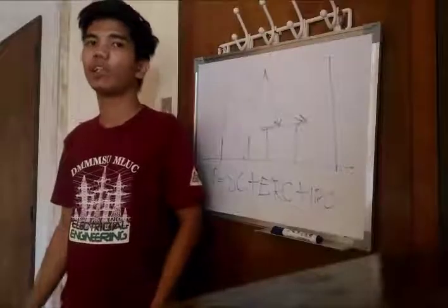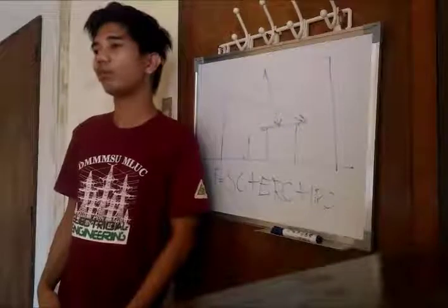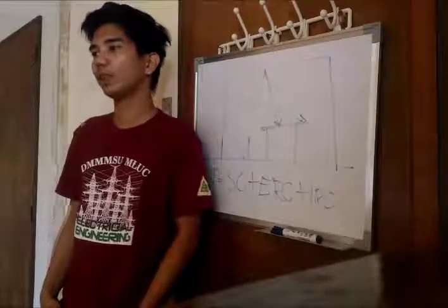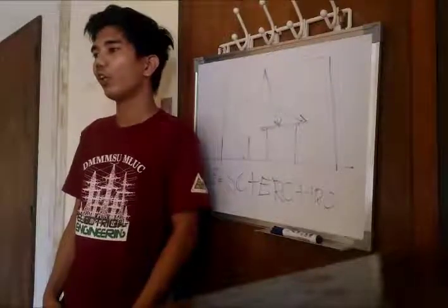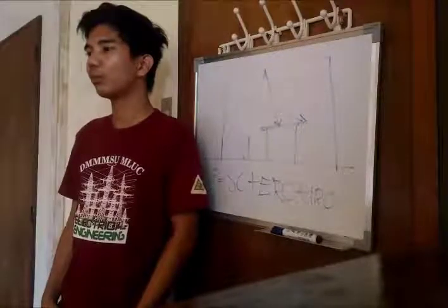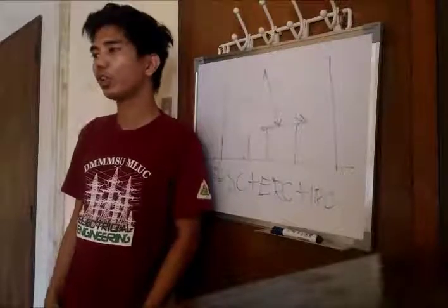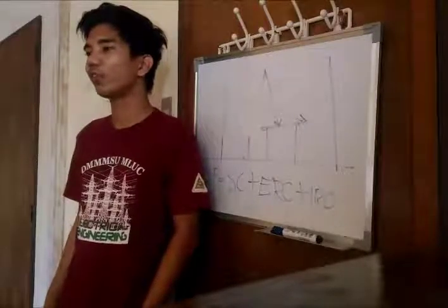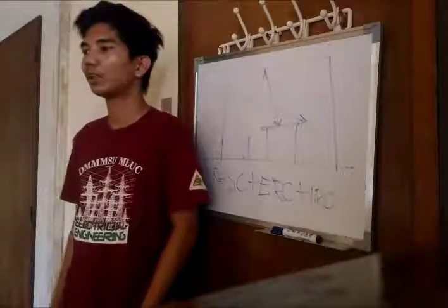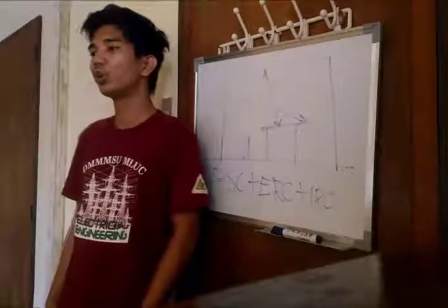Design elements: there are exterior elements. Exterior elements defined as overhangs can be useful controls for fenestration, in addition to blocking the direct beam from the sun. They will also reduce the amount of sky seen from within a room, thus reducing the amount of diffuse skylight admitted through the opening.